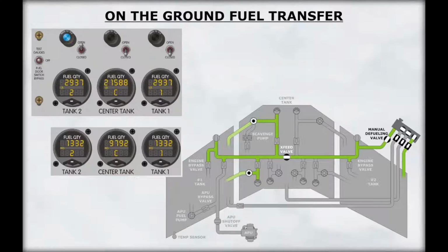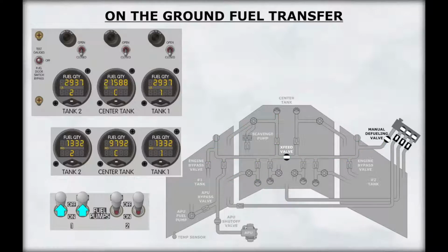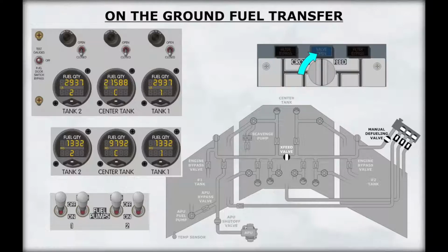To terminate the transfer, close the tank valve switch and the manual defueling valve. Also, turn off the boost pumps and close the crossfeed valve.